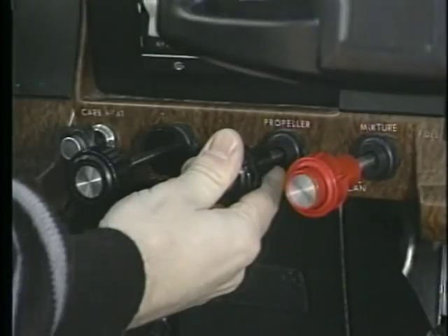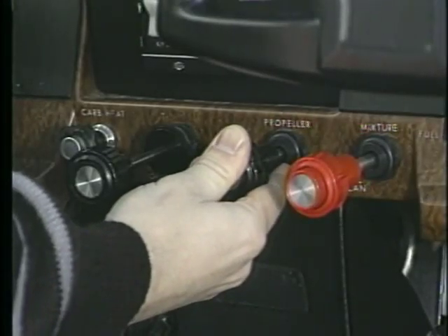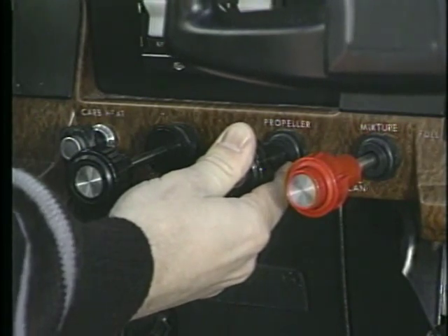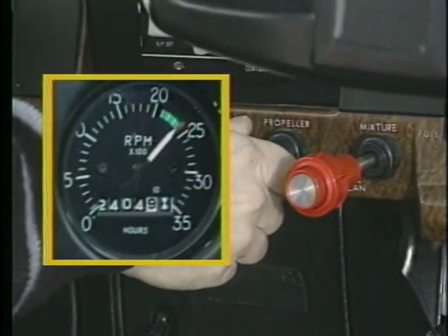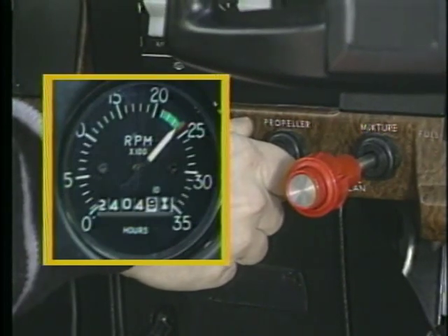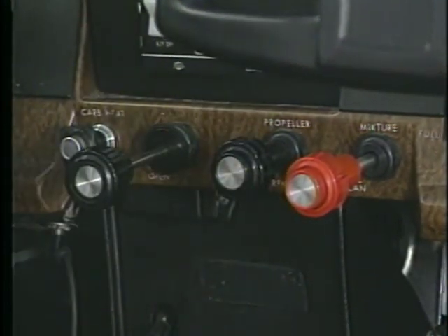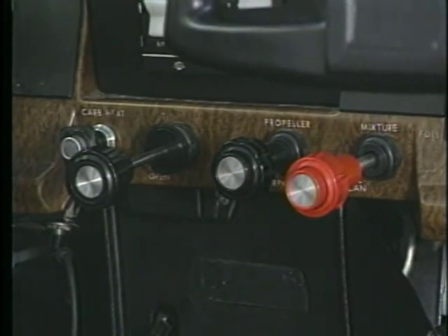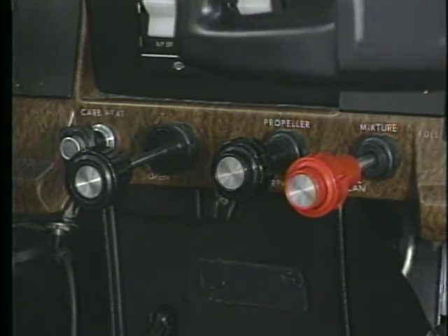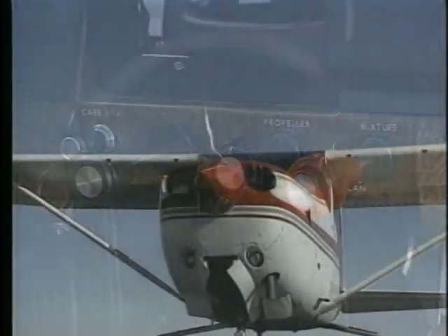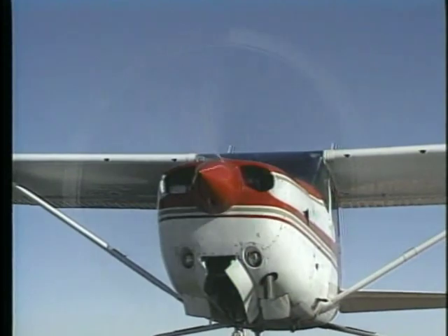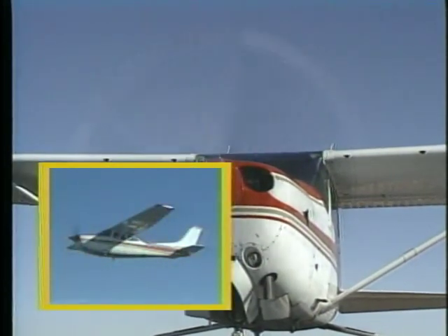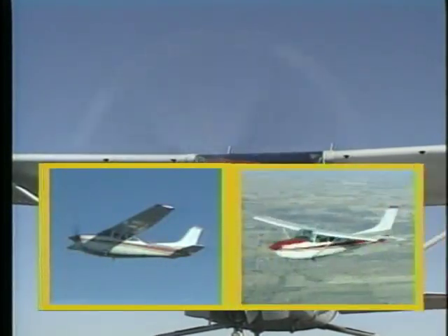The propeller control lets you change the pitch of the propeller blades, which regulates the RPMs shown on the tachometer. Your ability to select and maintain various blade angles and RPM settings for different phases of flight is where the efficiency of a constant-speed propeller is measured. Changing propeller RPMs is much like changing the gears on an automobile or bicycle, where a low gear is best during acceleration and a high gear for